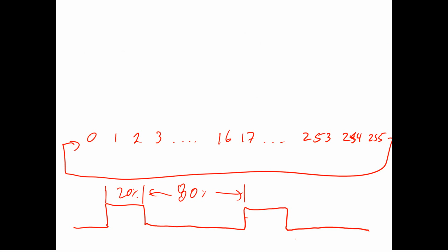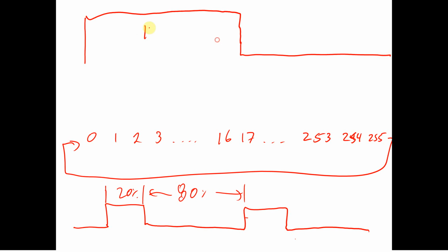So if I change this, it just goes high here, and then goes low at 17. Again, the scale is terribly wrong, as you can see. So ignore the fact this looks like a 50% duty cycle, because this is really 17 over 255, something around that. I might be off by 1. That's how we can use timers for pulse width modulation.